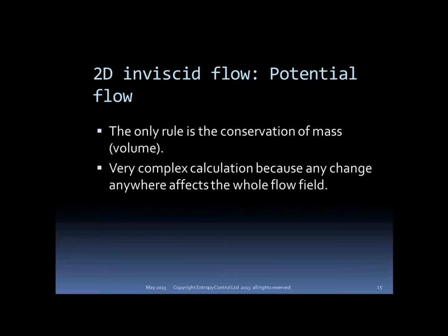So, how does the two-dimensional analysis work? We start with a two-dimensional model that depends only on continuity. If you place a two-dimensional airfoil in a simulated two-dimensional flow field, then mass and volume conservation allows for only one solution. That solution is a network of streamlines flowing in a frictionless way around the airfoil.